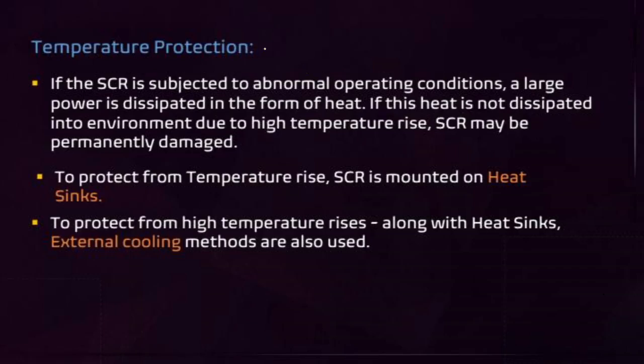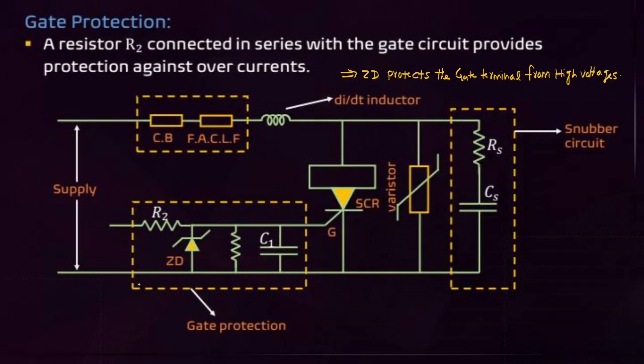Temperature protection. To protect the SCR from high temperature rise, we have to use a heat sink. If there is a very high temperature rise, we have to use external cooling methods, that is water cooling and air cooling methods, for temperature protection.